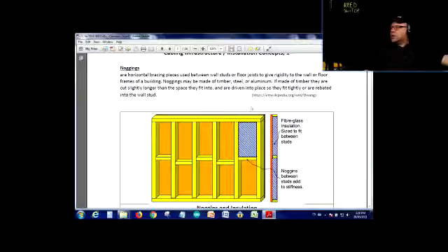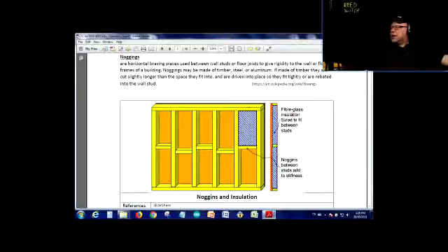Okay, so what do we have here? Yeah, okay, so we did that. Now, when it's a partition wall, quite often you're going to see fiberglass insulation. Now that can be a little stopper for you to run a wire. You're going to try to use the glass rods to push your way in through this insulation and get on the other side.